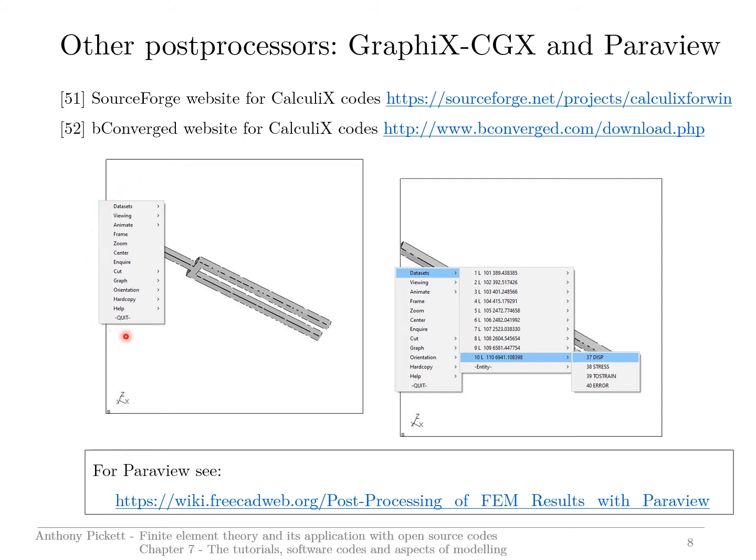And in here you would activate something, for example, zoom to zoom in or out, animate to show a sequence of pictures, different viewing angles. And for example, the data sets information is stored in here. If you click on this, which I'm showing here, then you get maybe a set of results. These could be, for example, eigenmodes in a buckling or frequency analysis. You then click on this and the next window opens and you say displacement, for example.